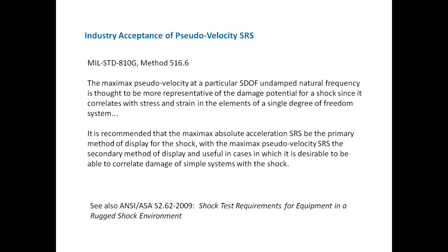So the paradigm has not changed yet. We're still primarily using absolute acceleration as the primary metric for SRS, but there is some consideration being given to pseudo velocity, and personally, I like the one-size-fits-all method of the tripartite or four-coordinate plot method, because maybe we should specify all our specifications in four-coordinate plot, because that has something for everybody.